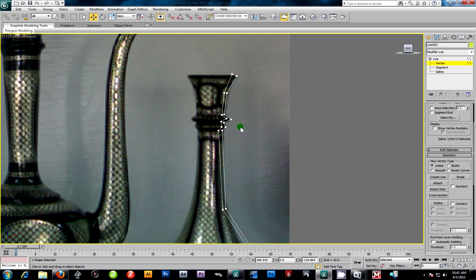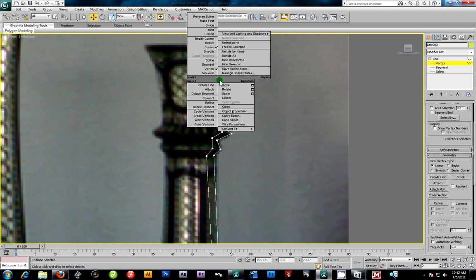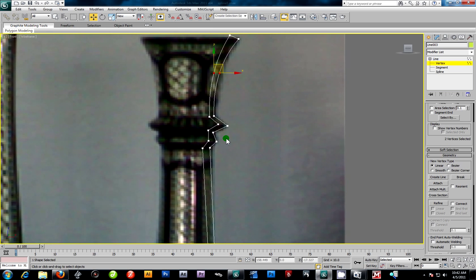Alright, so now I'm going to go ahead and smooth these out. So I'm going to highlight this, right click, smooth. And you know what, now we can do a couple things. We can fillet it or just right click and smooth it. In this case, maybe I wanted them to be a little more angled in. Actually, that looks pretty good. We can go about like that. But like I said, I can always come back and say, you know what, watch, I'm going to Control Z.